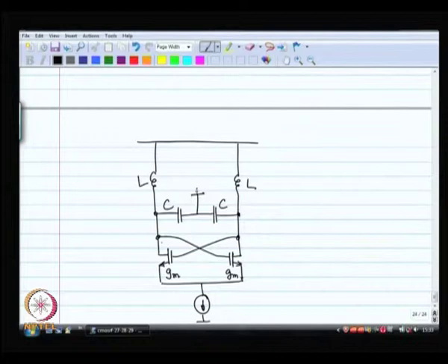There is CGD. Now, CGD can be lumped into the discrete capacitors that we have got over there. So, CGD is really between these two terminals, and I can lump it inside the capacitances that we already have over there. So, I need not bother about CGD, right. What else is there?